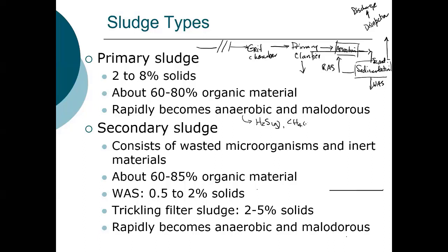methane gas, and CO2. What are the dangers there? Said it was malodorous, but what are the dangers? Hydrogen sulfide and methane are explosive gases. So one of the challenges is really during storage and making sure that all of the plant operators are safe from exposure, both they're toxic, but also from explosions.